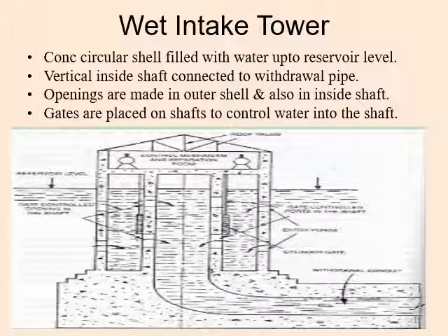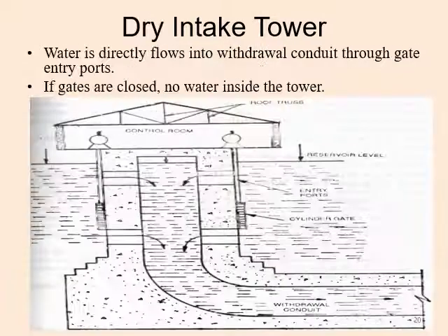Openings are made in the outer shell and also in the inside shaft. Gates are placed on the shafts to control or to regulate the water, how much quantity of water we will need to control into the shaft. So it is a type of wet intake structure.